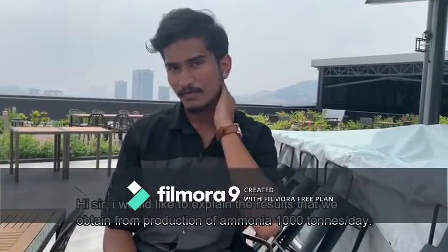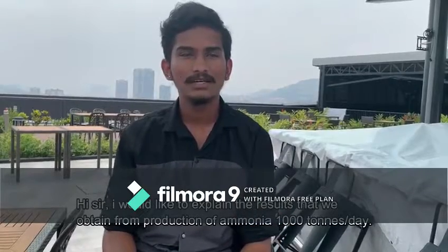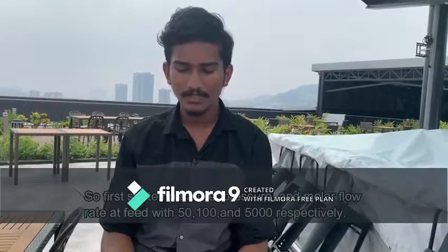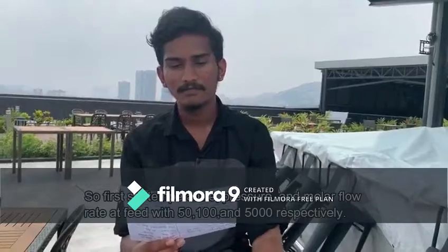Hi sir, I would like to explain the results that we obtained for the production of ammonia, 1,000 ton per day. So first, the feed temperature, pressure and molar flow rate are 50, 100 and 5,000 respectively, and the composition of the feed is 0.25 and 0.75 for nitrogen and hydrogen, and ammonia was 0.